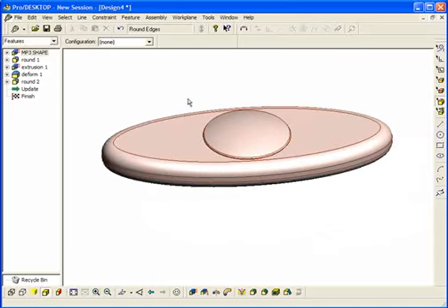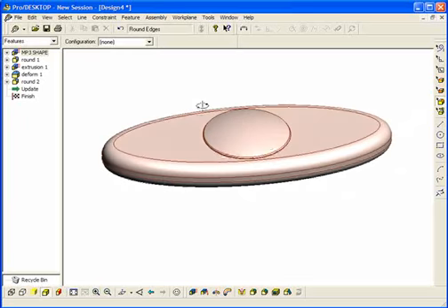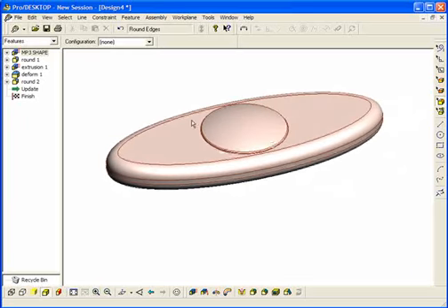Now I will show you another way of making a screen where you extrude it into the material of the body and subtract it from the actual shape. We need to delete the screen we have just made. So on the left hand side in the browser menu, select the extrusion that was the screen.